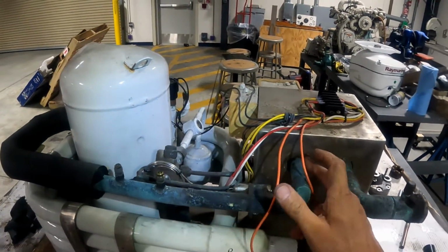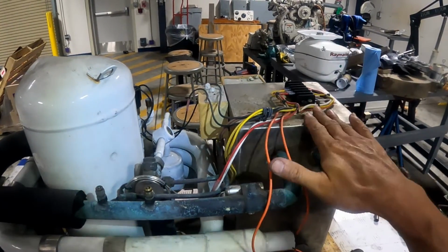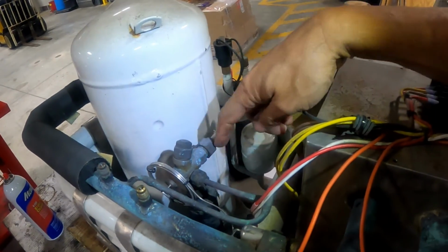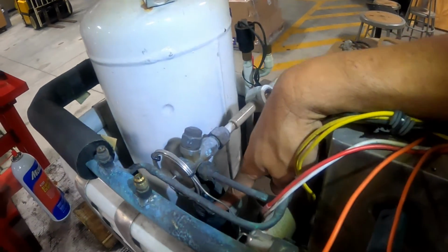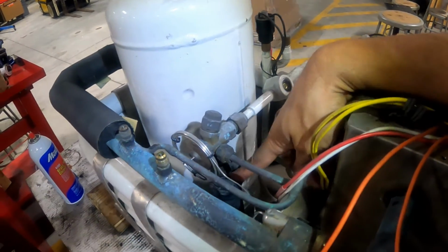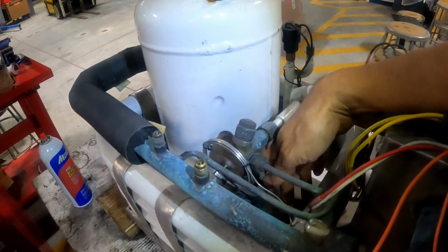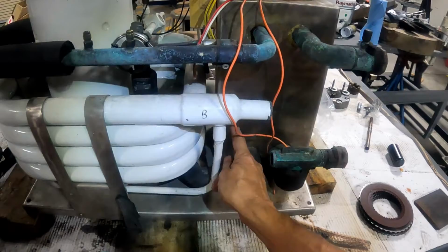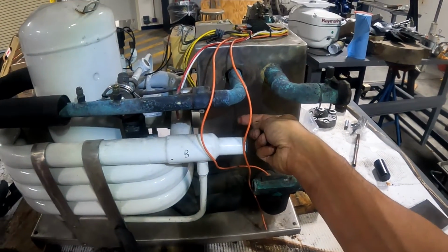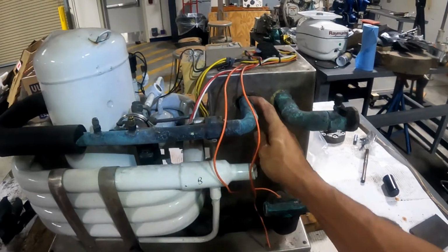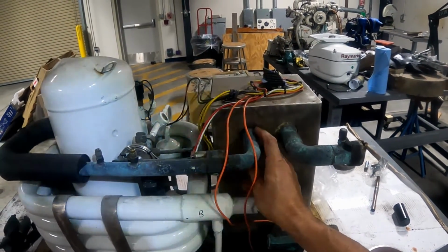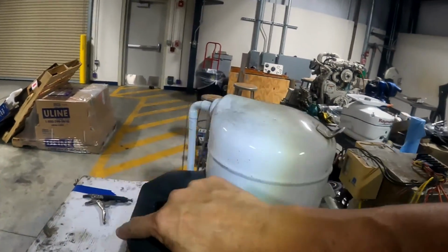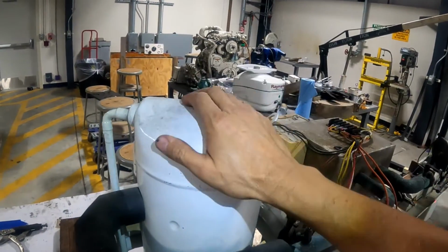This pipe is the return, the output of the evaporator. When the expansion valve opens, the refrigerant goes to the bottom right now. The pressure and the temperature reduce dramatically and freeze this pipe. This pipe is protected with insulation because it's frozen. And that frozen pipe enters at the bottom and passes here and the refrigerant starts to evaporate. And right now, at this point, the refrigerant is evaporated, but it's too cold, of course. It continues as evaporated vapor and enters the compressor, and the cycle starts again and again.